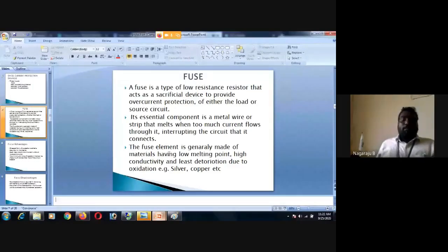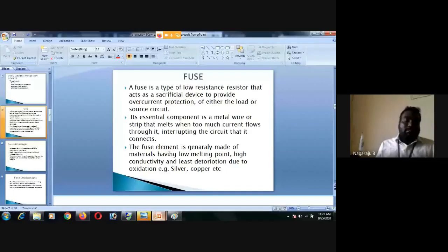As well as that, power fuses are employed where the system voltage is 34.5 kV or higher, and the interrupting requirements are greater than the available fuse cutout ratings.